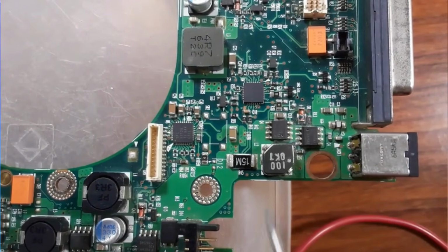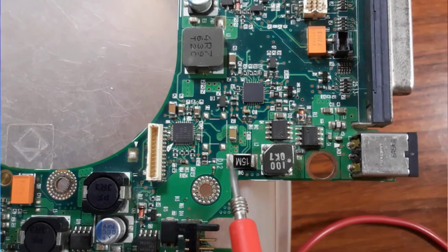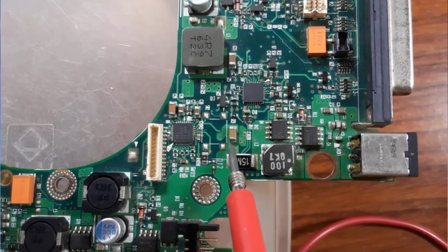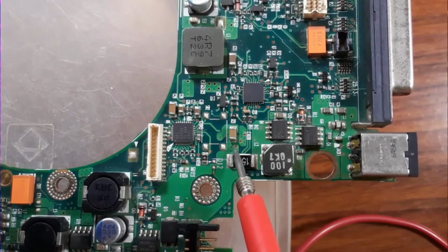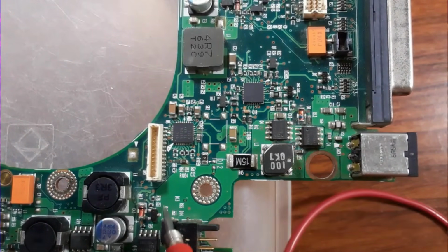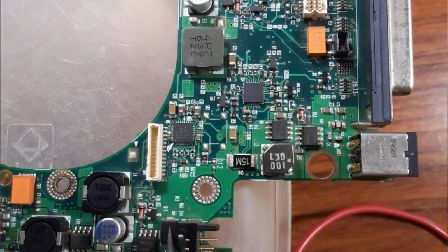After that, the signal or the 19 volt will pass through this resistance and go where? As you can see, we have this green color here. It will go to this capacitor. This capacitor is connected to this resistance because, as you see, we have the same path here, the green color, and also it will go here, as you can see, to this transistor and to this diode.